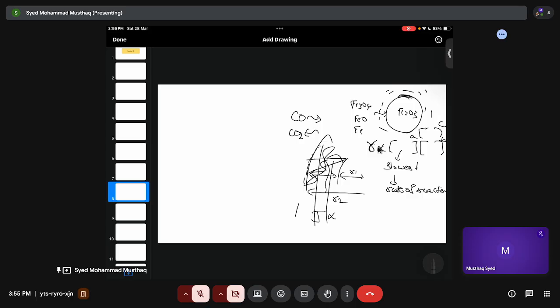In steel melting units, you have the BOF, which is the basic oxygen furnace, or you can go for the electric arc furnace. In the electric arc furnace, you have the leverage of using how much liquid metal or scrap you want. The basic advantage of the electric arc furnace is you can go up to 90 to 95% of scrap. Yes, it takes energy, but there is no limitation for that.